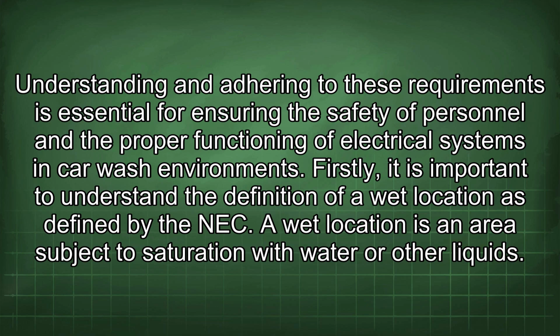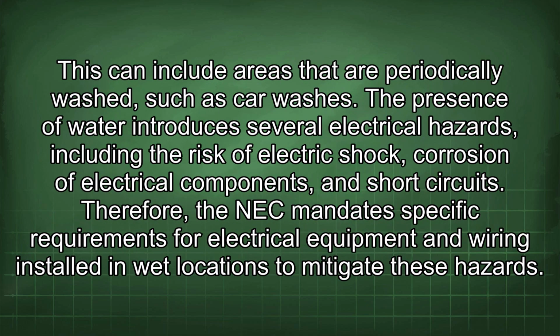Firstly, it is important to understand the definition of a wet location as defined by the NEC. A wet location is an area subject to saturation with water or other liquids. This can include areas that are periodically washed, such as car washes.